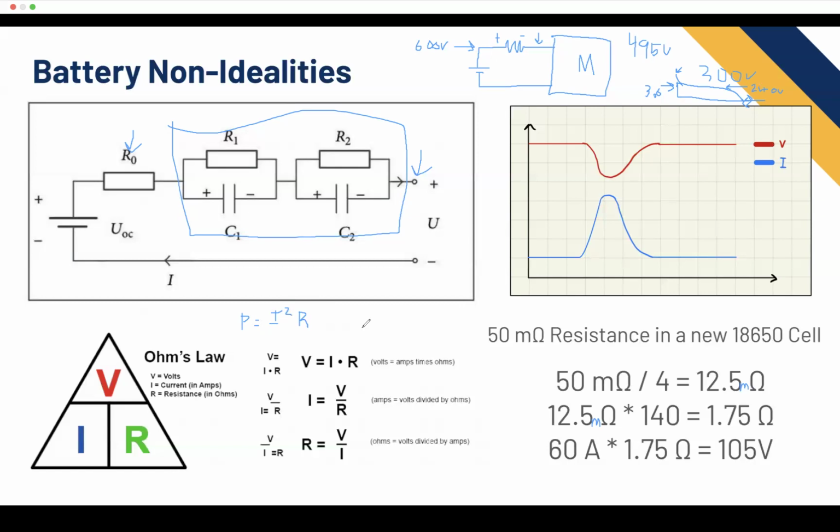That's a lot. We don't want to be burning that much, so you want to reduce that number as much as possible. That's also why we run high voltage, low current to try to reduce heating losses, or at least that's the idea, that's the goal.